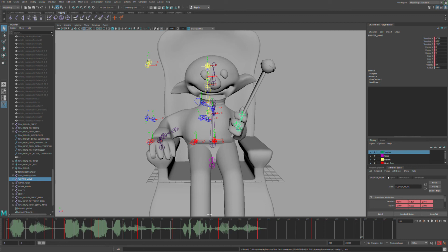These min and max values are basically responsible for converting the data from the Maya files, which is the rotational data, like the angle values, into values based on the min and max values using a formula that allows it to convert into percentage values, which causes the motor to rotate.